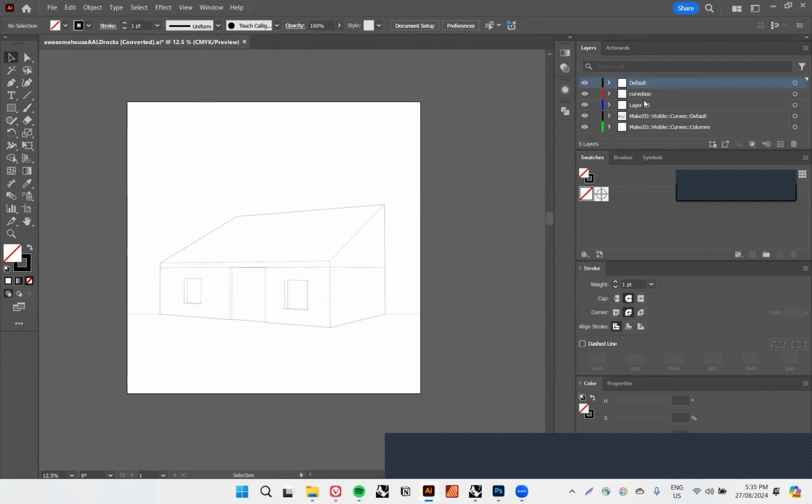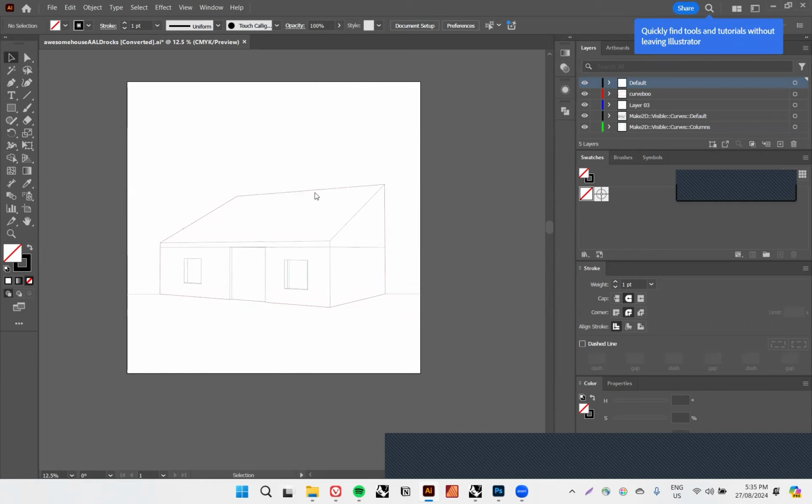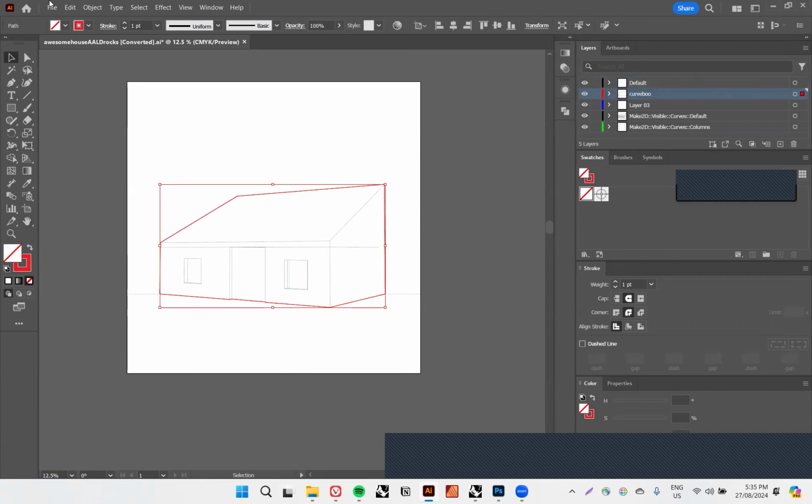You want to maybe talk about layers? Okay. Or line weights? So the most important thing for your drawings right now is going to be line weights. And in ARC 100, that is what you're going to be learning, and they're going to stress it a lot, because that's how you can read a drawing, especially when you have complicated drawings. Line weights push the important information to the top. Cody is laughing in the back because I don't use line weights, but for this demonstration, Josh, I will do the line weights.